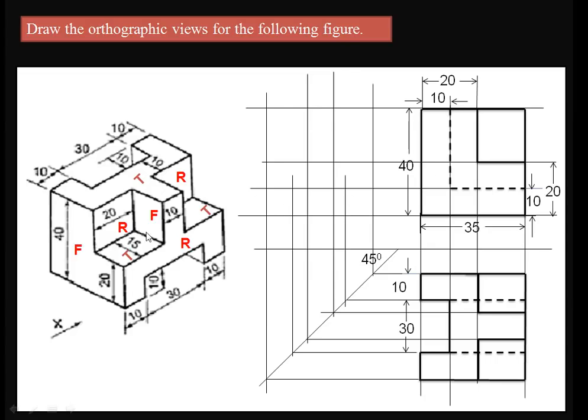So assume here, again analyze the right side view. In right side view we can see this surface in a shape of T or an edge connected to the U shape like this. And similarly we can see this surface and this surface. So totally it will be like a rectangle. Again in that rectangle we can see certain edges. How can we draw those edges? First I would like to show you the two last edges. These two last edges will be continuously visible. Similarly this top edge is also continuously visible as a straight line.